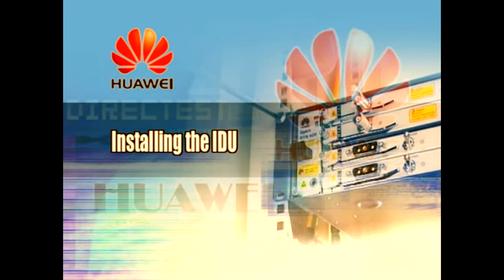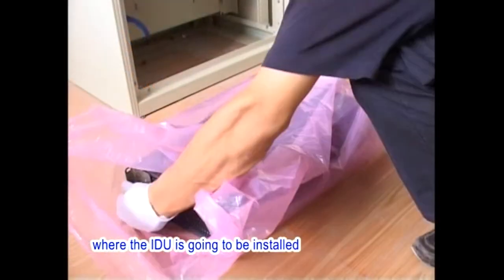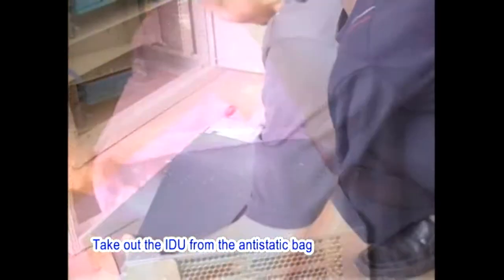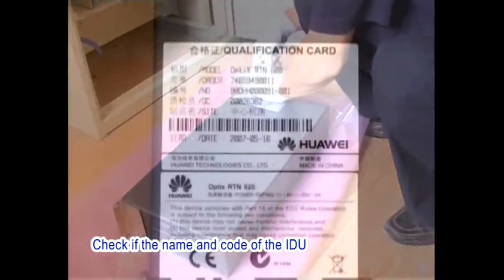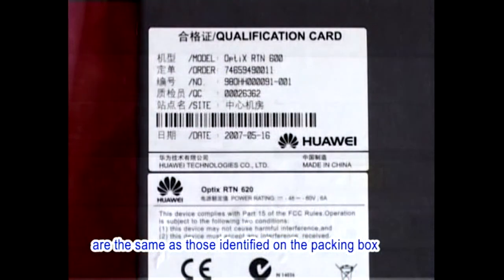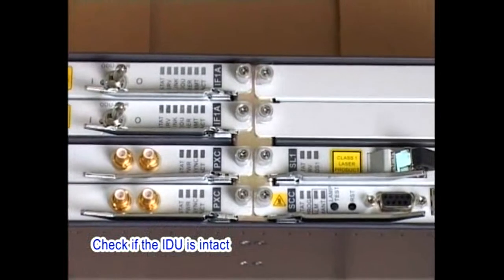1. Installing the IDU. Confirm the position where the IDU is going to be installed. Take out the IDU from the anti-static bag. Check if the name and code of the IDU are the same as those identified on the packing box. Check if the IDU is intact.